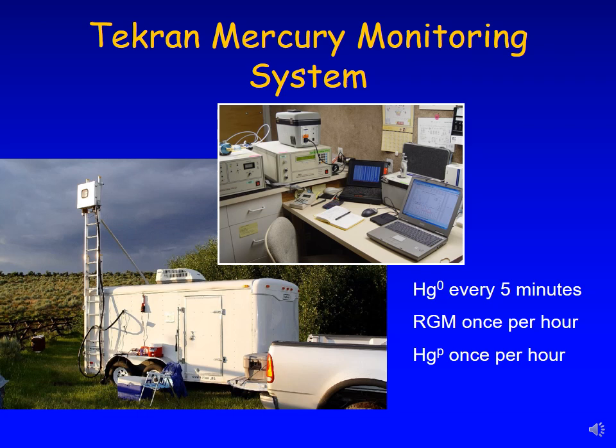Just to show you how sensitive the instruments are to contamination, I have metal fillings in my teeth, and they are an amalgam of mercury and other metals. If I were to breathe on the inlet, the mercury coming from my fillings is enough to trigger a response in the instruments. So just to give you an idea of how sensitive these instruments actually are.